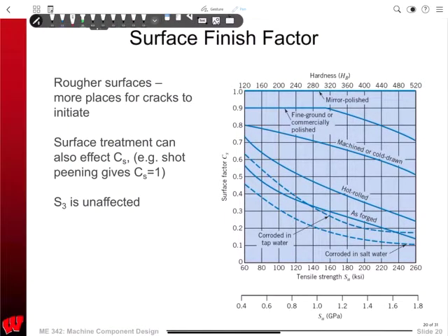And then this is really, I should make this the first one, but for whatever reason I didn't, the surface finish, right? Typically, bending stresses cause things to fail, right? And the bending stresses are greatest at the surface. So if I run down to the machine shop, if someday it opens again, and I machine this thing, here,